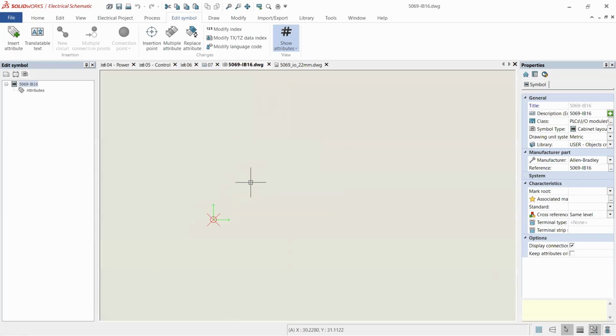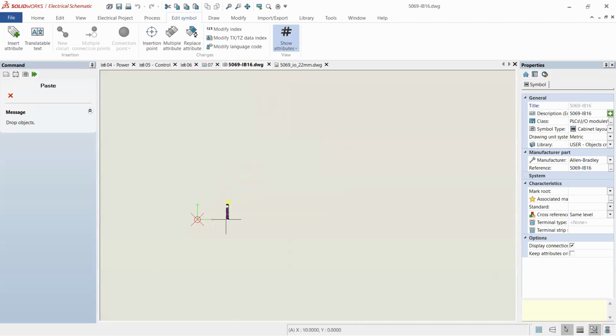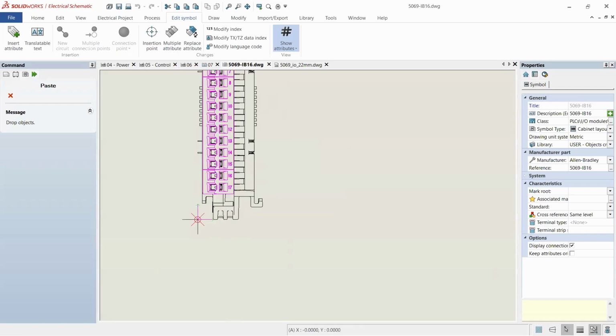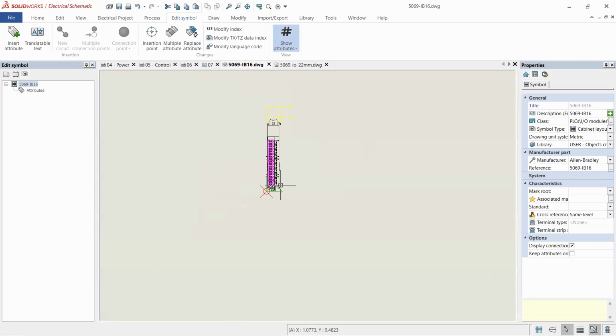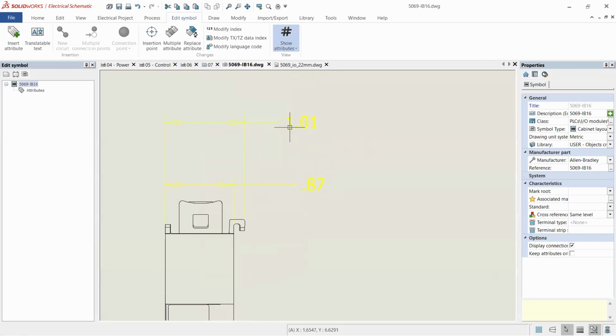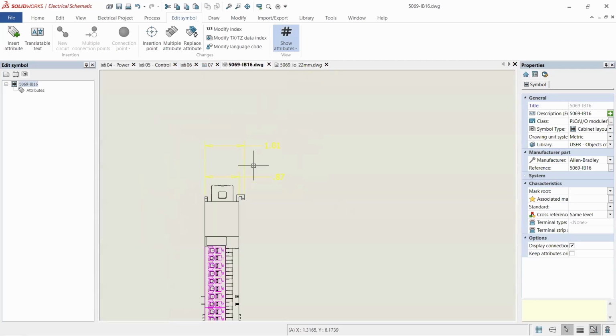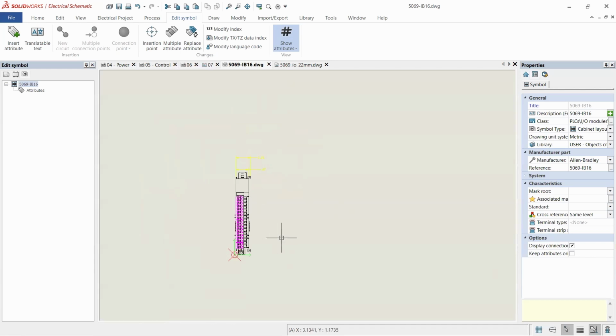So we've got the drawing already. I can just literally paste. It doesn't really matter where we drop it for now. I'll move it later. It takes a second sometimes to really think about it. There's a lot of detail in here. This now is 1 millimeter, right? Literally, that dimension updated. It is 1 millimeter, and it did that because it thinks what we pasted in was in standard. It's a conversion problem.